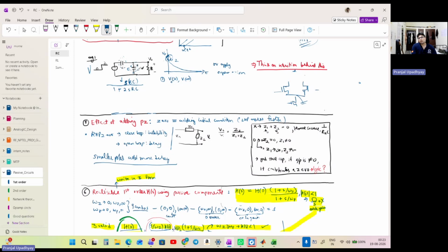But let us say that I have a cap over here, I have some cap over here, and here I have my active mirror load, and here is my output, V naught or V output, right? So here these are three caps, and I want to understand which of these will contribute to a zero. So what I'll do is ground this capacitor and check the output. My output is zero the moment I short it. This implies that this capacitor won't contribute to a zero.